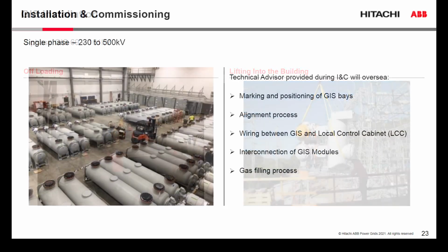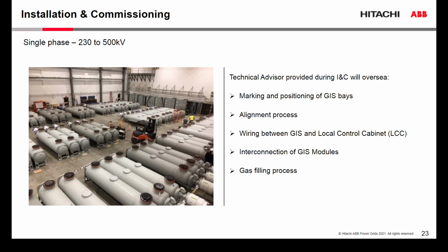While the three-phase technology is highly pre-assembled, the single-phase design, depending on layout, comes in smaller shipping units. We see, for example, on the left side, the picture with a larger number of 345 kV breakers, which are assembled here. You need to make sure that you get through such a puzzle, have it assembled the right way, and get your finished product. Your finished product is the gas insulated substation.